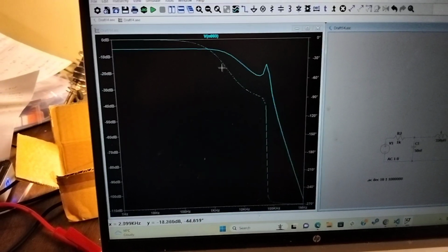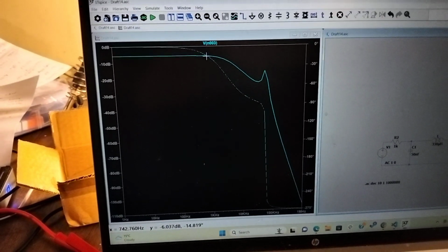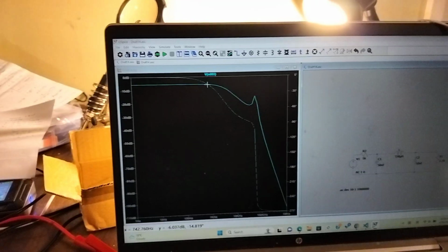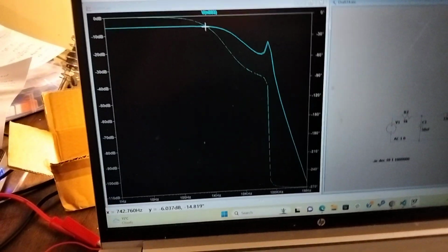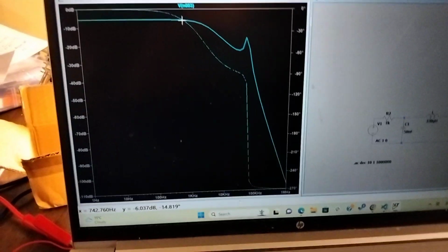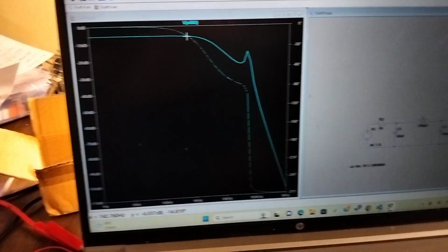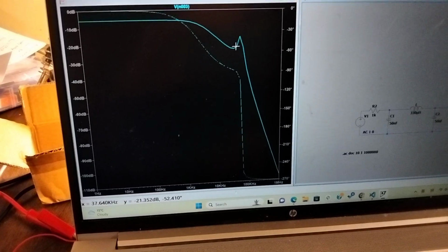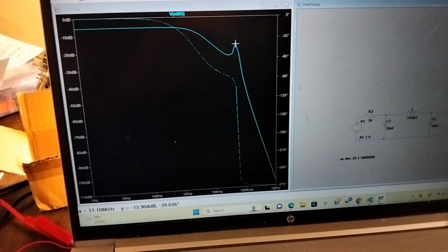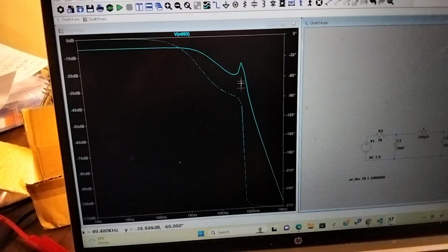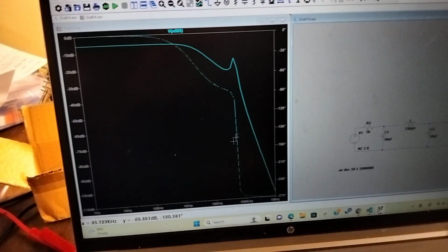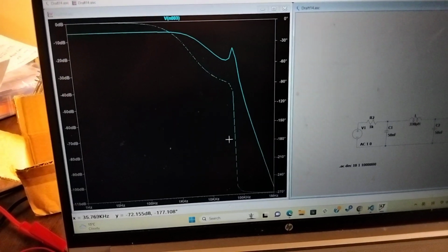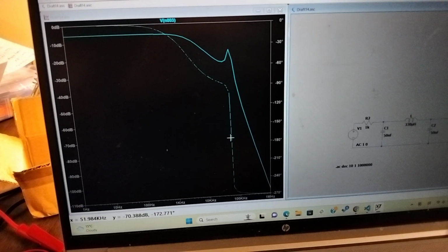So they'll destructively interfere, and they don't get added up with the same factor in the loop. So the resonance frequency is actually not determined by the resonance peak. It's actually determined by when the 180 phase shift happens. So that's really what's causing a particular frequency to be selected by this filter.